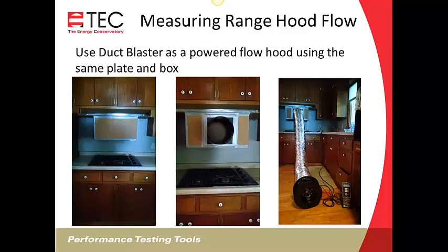And now we've got a second option for measuring flow. And remember, the Duct Blaster Fan can move up to 1300 CFM airflow, or even more than that, really, because the kitchen fan is doing part of moving the airflow. So now we're moving air at no resistance, so you can measure flows of very large exhaust fans using this method.